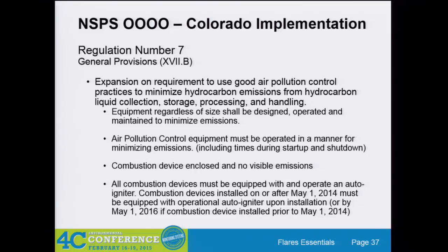Your air pollution control equipment must be operated in a manner to minimize emissions, including startup and shutdown. So again, I think a lot more requirements over Quad O. Combustion device, no visible emissions. Enclosed, you can't have any leaks in your closed vent system. Interesting.